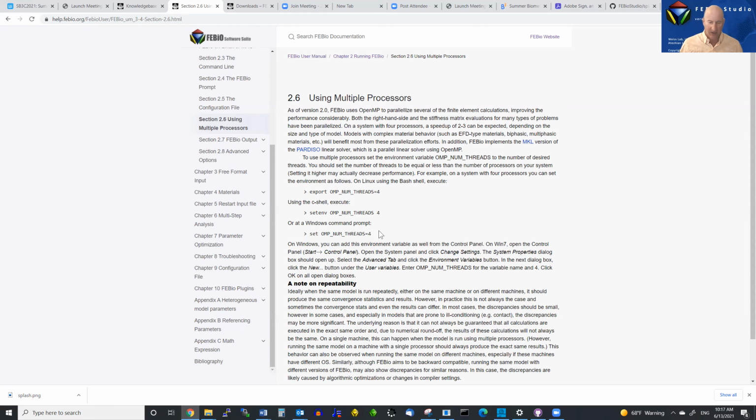That's simply a characteristic of assembling the stiffness matrix: how many degrees of freedom are in it determines how much memory it takes to store it. The other aspect of stiffness matrix storage is whether the problem results in a symmetric or a non-symmetric matrix. Most elasticity problems that don't involve contact result in a symmetric matrix.